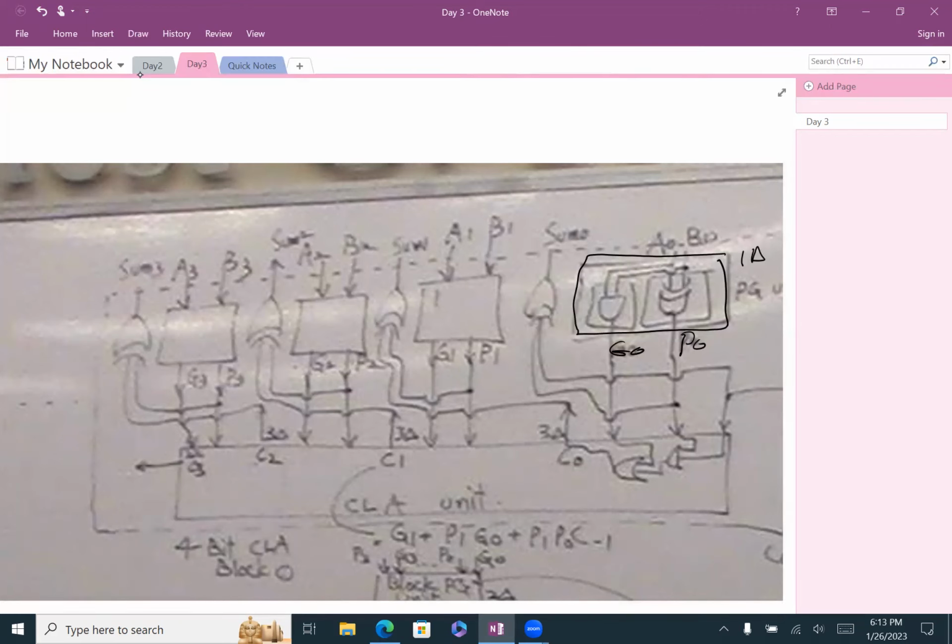All right. So this block is trying to find the B and G. And here we find B1 and G1, correct? And same thing for bit number 3, trying to find B2 and G2, B3 and G3, right? So when we find B0, B1, B2, B3, how long is it going to take us to find those? 1 delta for all of them, correct? So they are not depending on each other. We are depending just on the input.